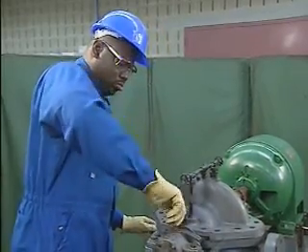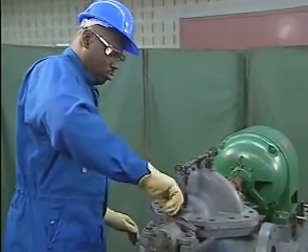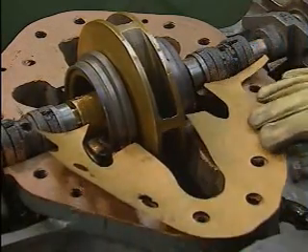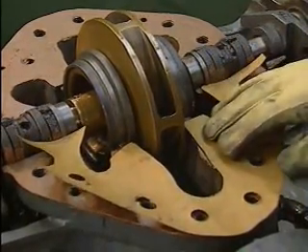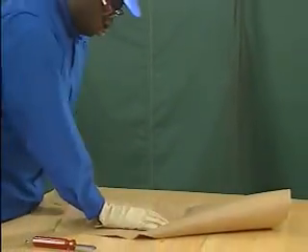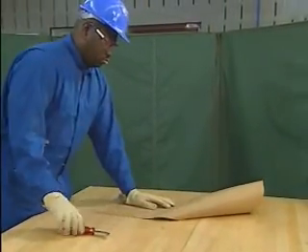Fluid system components require regular maintenance. Because strong seals are vital to the integrity of a fluid system, gaskets are often replaced as part of any regular maintenance routine, whether they show signs of failure or not. Though many flat gaskets come in preformed shapes and sizes, some common replacement applications call for gaskets that are cut from sheets of gasket material.